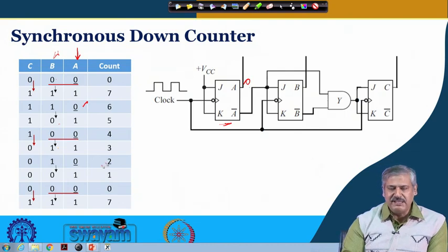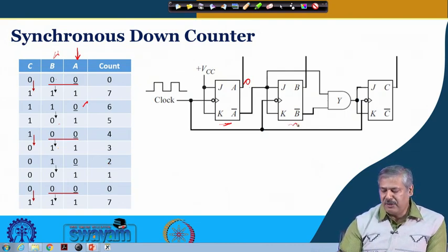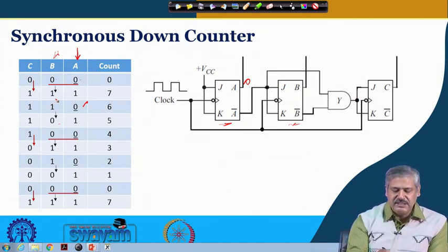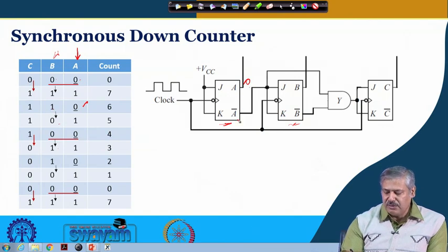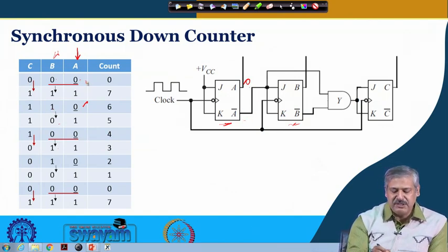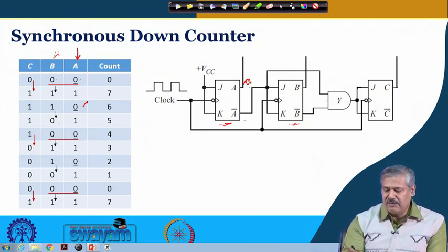Now, to make change happen in a flip flop, we need 1 1 at the input, right, just in the toggle mode for a JK flip flop. So, for 0 it is changing. So, instead of A, if we put A bar, that means whenever A is 0, 1 1 will be fed as the input to J and K, and with the clock it will toggle. So, that is the way the connection has been made here, clear.